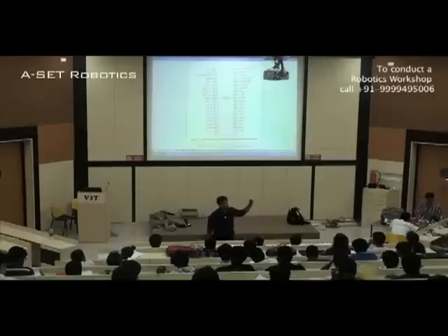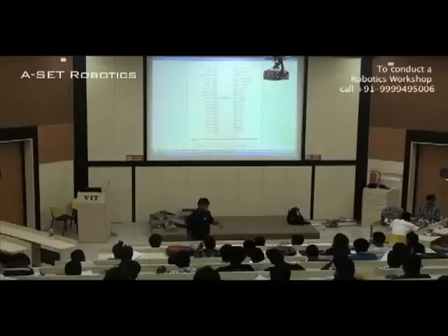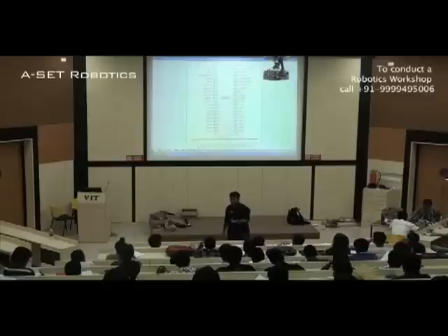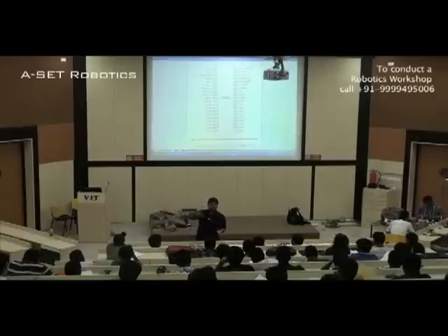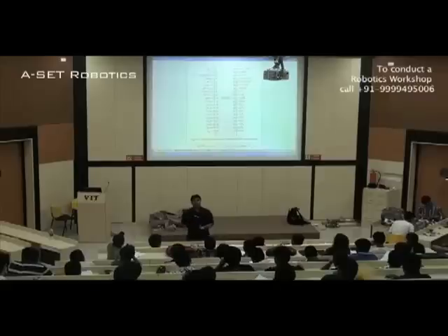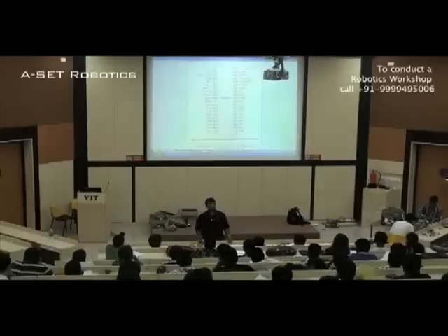It takes the control of the bus from the microprocessor and then transfers the data, because to transfer that data at a high speed, the bus has to be used. And the bus is in control of the microprocessor. If it is in the control of the microprocessor, then DMA cannot work. So the authority of handling the bus is taken from the microprocessor. That is the work of DMA, direct memory access.